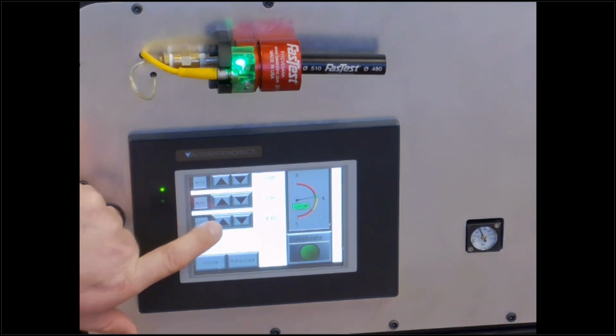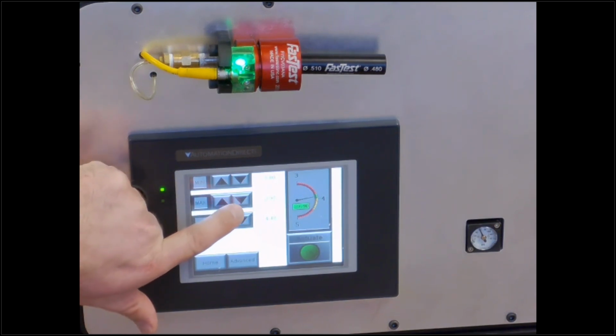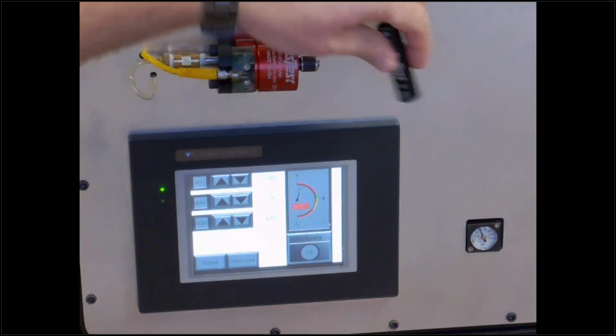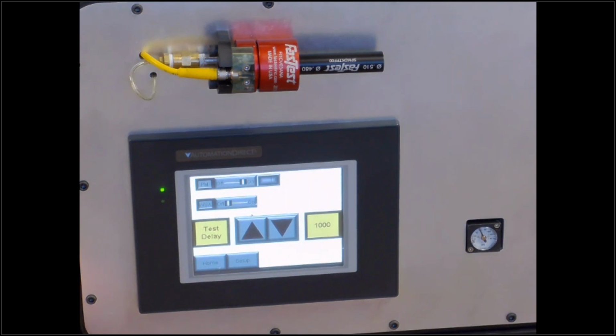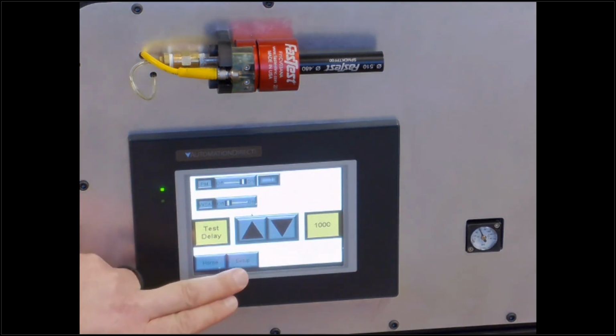I'm going to add a little buffer in there. You always want to have a little bit of a tolerance around where is a good connection. Now if I deactuate and put on the smaller end, you can kind of see where that piston lands. It's at about 3.4 volts versus the 3.8 that is actually a good signal. We also have an advanced menu where you can set some delays. We're waiting for that signal to be good for 1 second for you to get the proper response.